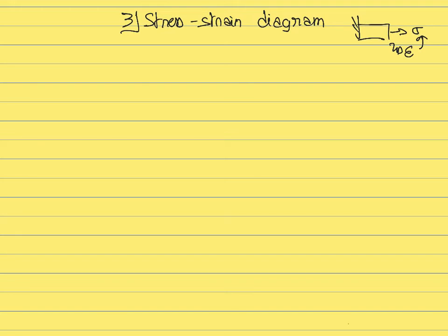In this case, we are going to focus on the stress-strain diagram in the case where you fix the deformation. So in this case, it's going to be displacement control. You fix the displacement first, you fix the deformation first, and then you measure the corresponding stress within the material. So we are going to draw what this stress-strain diagram looks like in different types of materials.